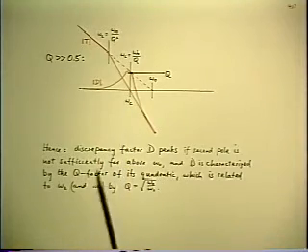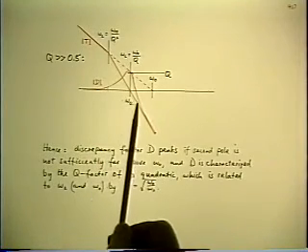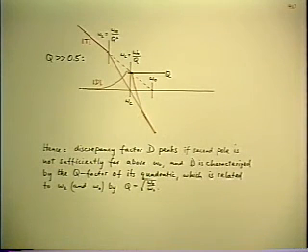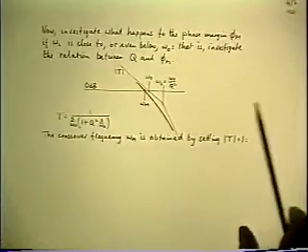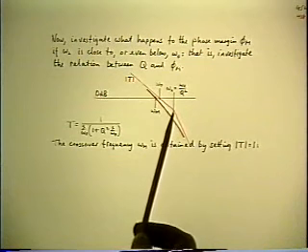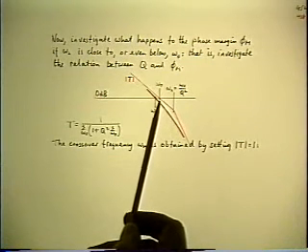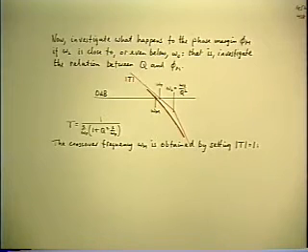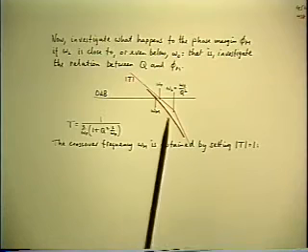So far I've just asked you qualitatively at each case what's the phase margin, but we can actually get a quantitative result. Here's how we do it. Here's the general case, where I've drawn the second pole in T a little bit above the original crossover at omega 0. All I have to do is calculate the phase margin using its definition.